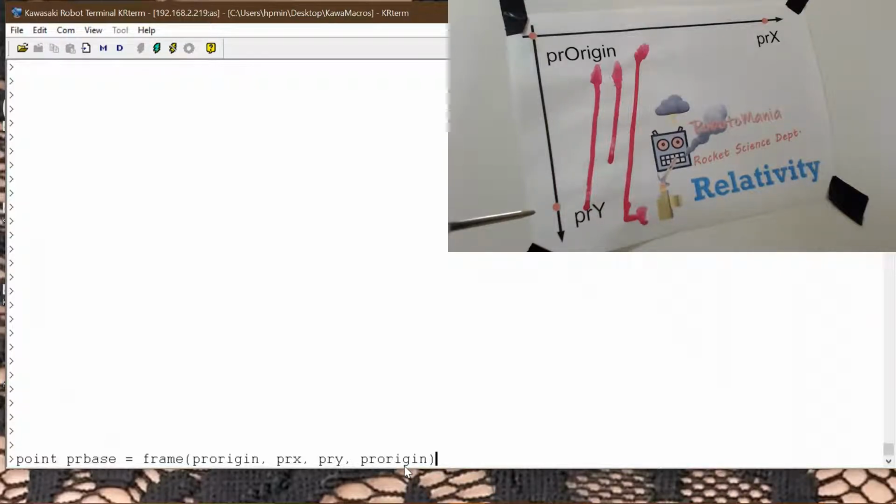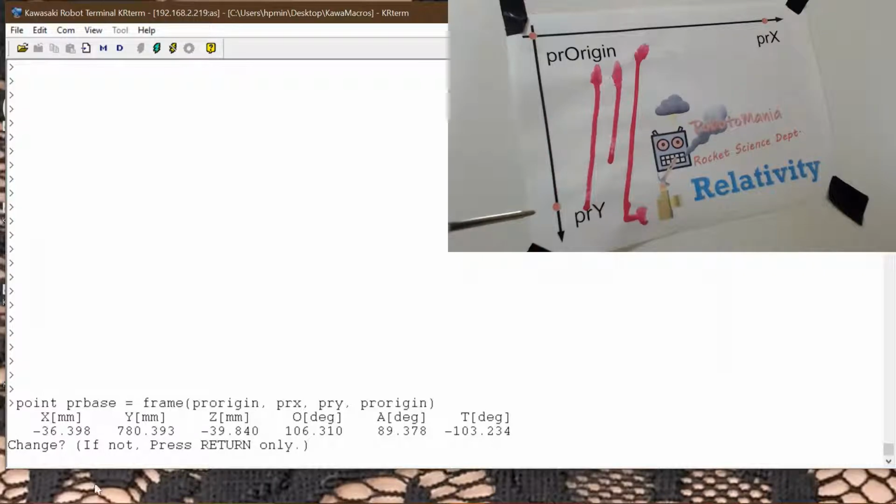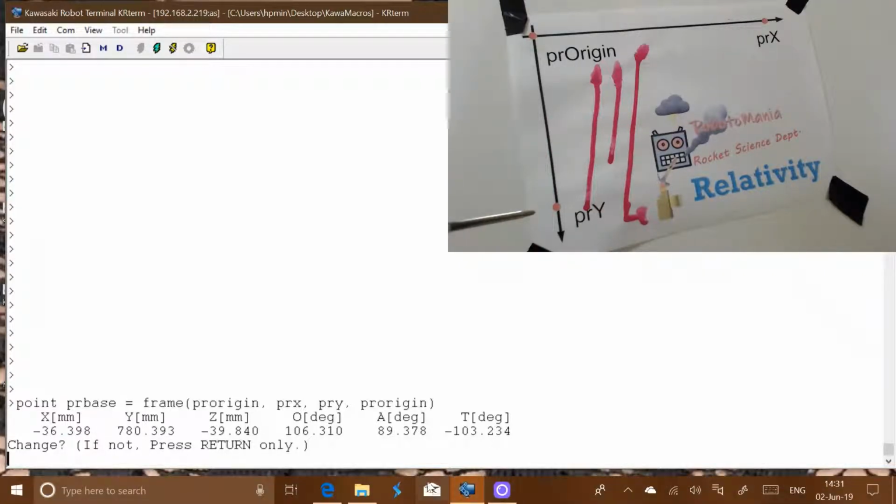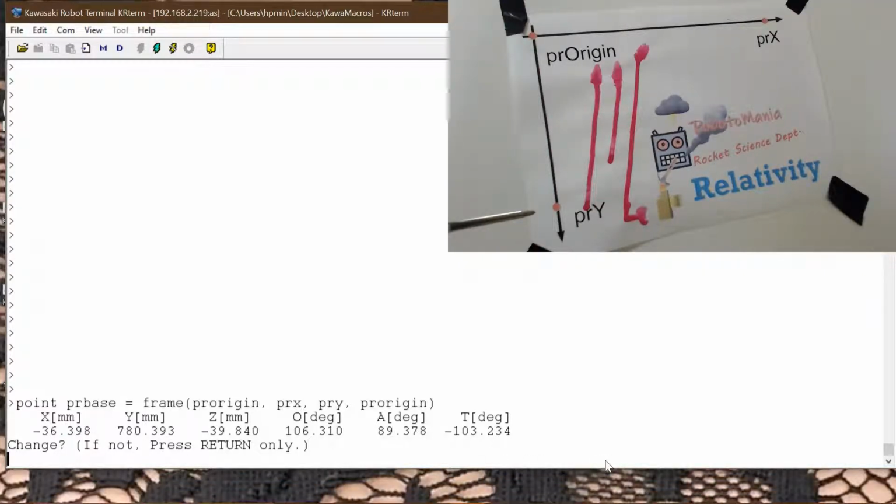will be used to specify the robot configuration, the wanted or the preferred robot configuration during operation in that specific frame. Left eye, right ear, wrist up, wrist down, and so on. So therefore we need another point which is just an example of how the joints need to be configured to operate in that frame. So let's go and hit enter and see what it gives. Yes, we have a point which is defined, and we may as well just use it.